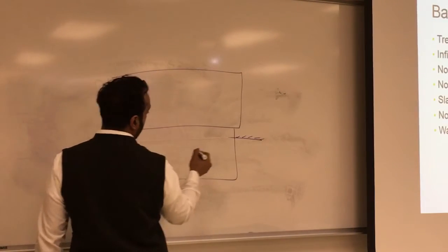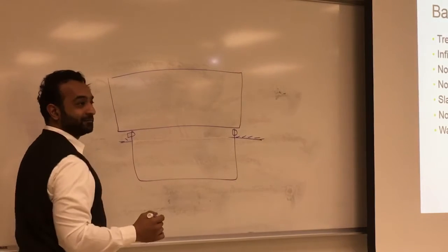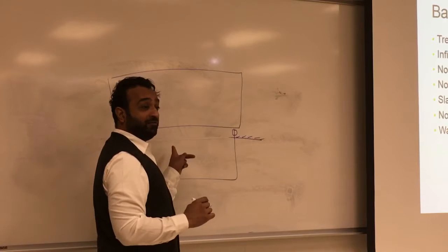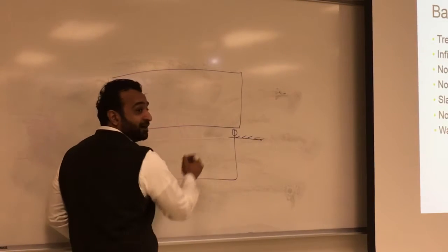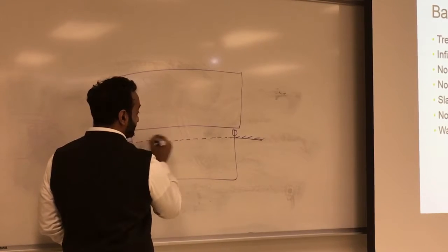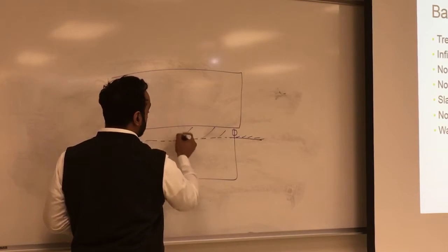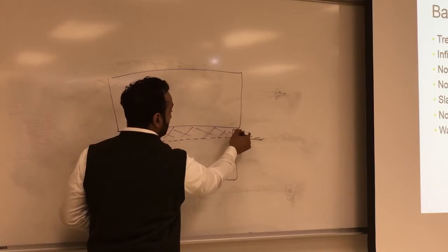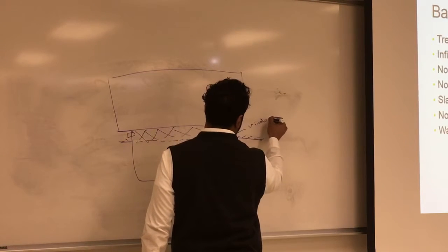It's the first floor. And usually you have windows here, right? You have more than one window, you just put them all together. But when you do the infiltration for the basement, and you do the volume, you do not do the entire volume. You do this volume only, 2 feet above the grade. That volume only is what you include in the infiltration for the basement. And these are your window area for the transmission.